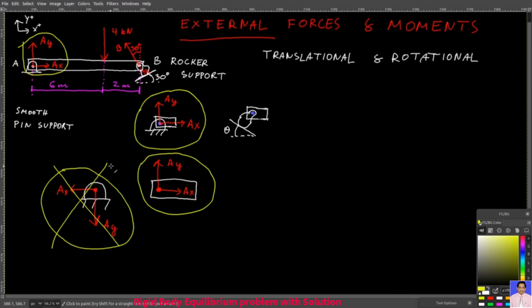This would be false. When I have a body and I draw a free body diagram for it, and I list all my reaction forces and moments to that body, then those reaction forces and moments are the ones that the supports apply to the body itself.